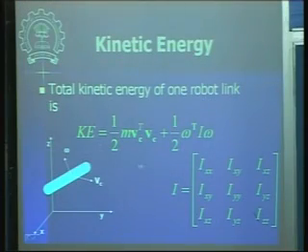Okay. Now what is the rotational part? The rotational part consists of half I omega kind of a term, but in this case you will observe that your I, which is the inertia matrix, is in general given by all these elements. Okay. So you have these diagonal entries for inertia of the rigid body about the axes of the coordinate frame, and then these are the cross coupling terms. Okay, and then this omega is a vector of the angular velocity of this rigid body or the rigid link of a robot.